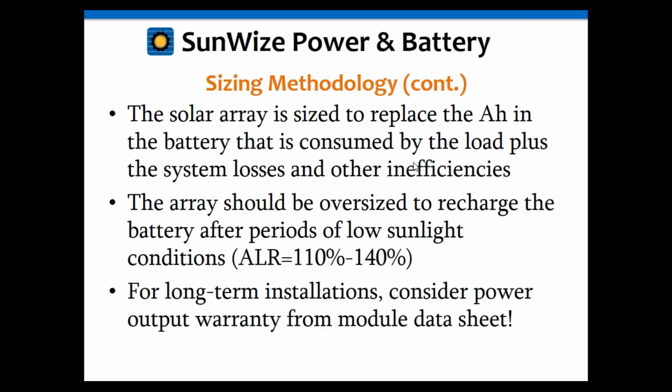And if you're familiar with our other webinars we've done, we talk about how if the batteries don't get fully charged periodically, they can sulfate. And again, that's the problem. If you go to too big a battery, that can be a situation. So bigger isn't always better. So it's best to have a battery sized appropriately to your site and your situation. And if you do have to go to a big battery like that, make certain you oversize the array such that you can recharge that battery quickly, or at least fast enough that you're not going to have a sulfation issue. So if you do oversize the battery, you have to oversize the array to compensate for that.